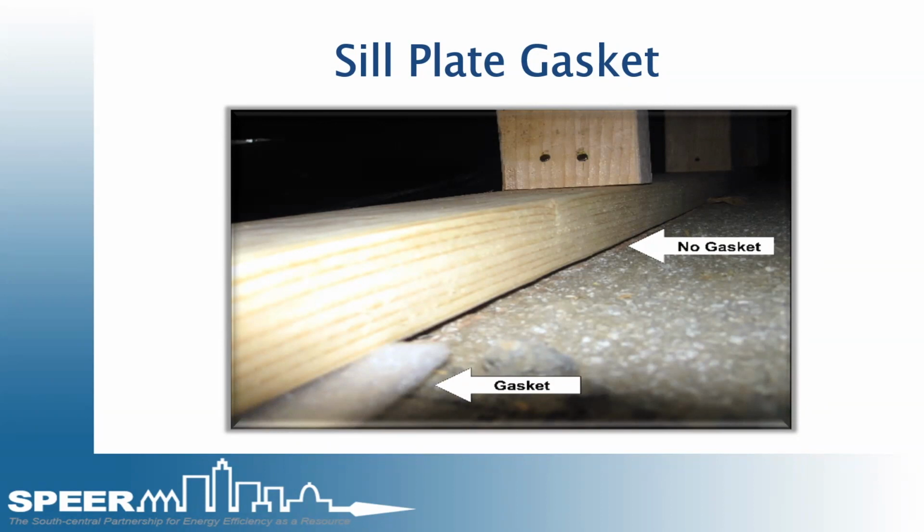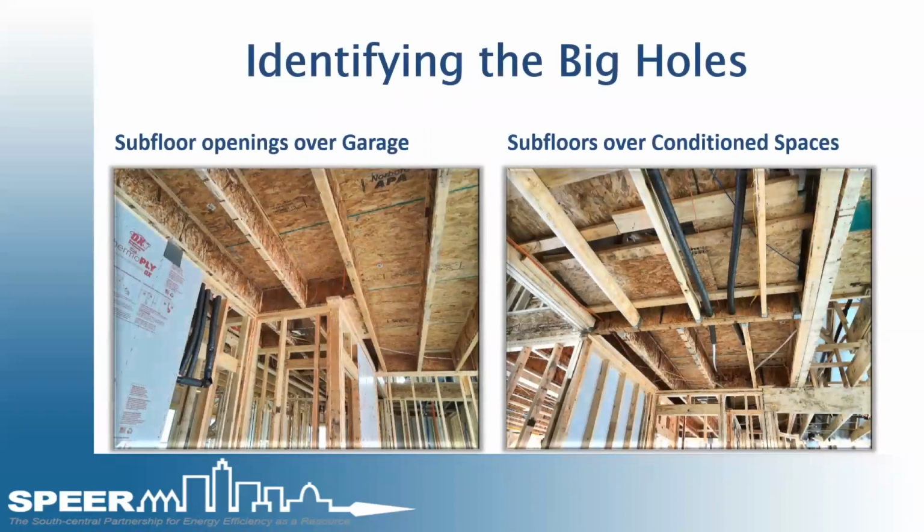What we always did was, if they missed this gasket and didn't have it throughout the house, we usually asked them to lift the plastic drainage plane on the outside, below where the cladding is going to go, and actually caulk the outside of that. No, it didn't help with moisture stop from wet concrete, but there's no fix for that once the framing member gets added to the concrete itself. But it did help with air penetration and airflow through that base plate at time of testing at final. So checking that is key.